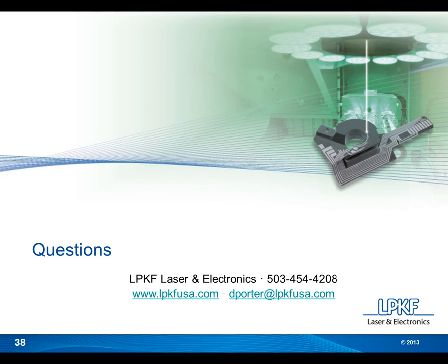The other way you could do, typically on higher temperature thermoplastics, is you can actually drill through thinner areas on the substrate, and you get a very tight aspect ratio that way. So you can get a very small hole, and it does activate the sides also, so you can then plate that through. Can you overmold? Yes, you can overmold parts. I've seen paint on those very thin drilled through holes. I've seen paint basically cover those up. So yes, you can end up with a sealed through hole on these parts.